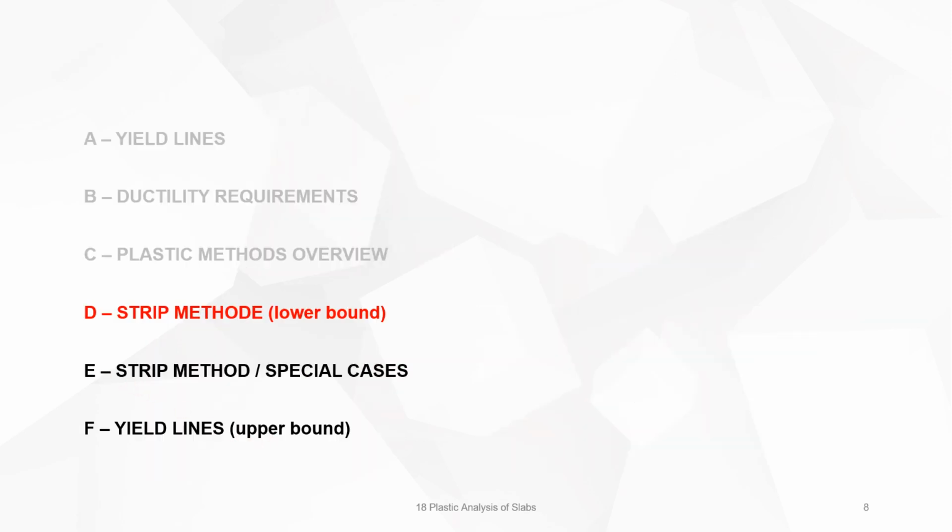Now we will look at the strip method. In the equations from Kirchhoff-Lagrange, we have seen that the second derivative of the bending moments, which is in fact the first derivative of the shear force, is equal to the ultimate load.